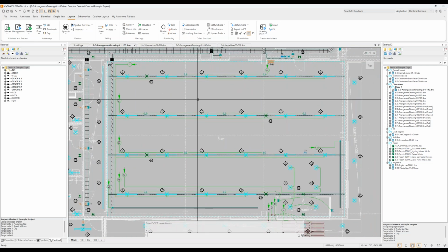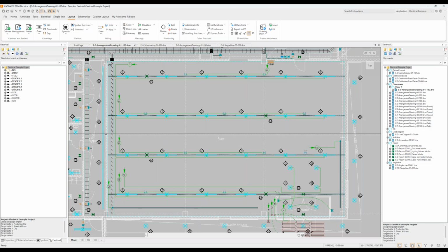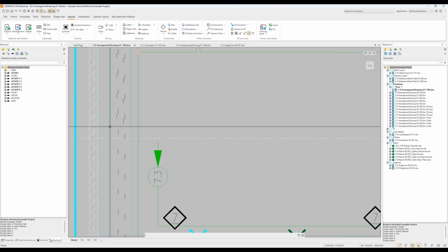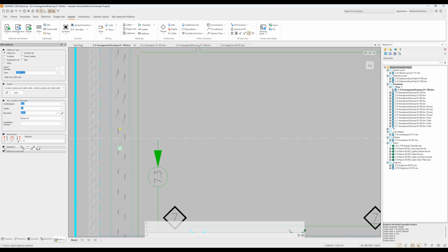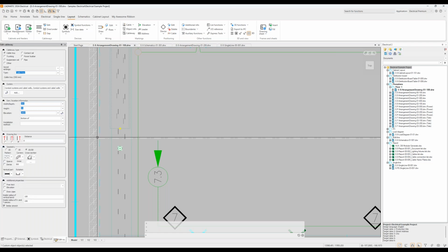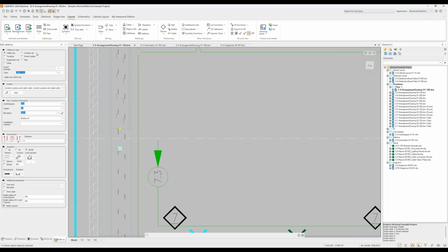Okay, that was just a quick example of how things are connected in electrical regarding cables, feeders, and distribution boards. Then let's move on to maybe doing more of the design of the drawing itself. We have the cable trays, cable ways, however you want to call them. We already have some existing things here that we can use as our base point. You can draw the cable ways, some trays, trunking, suspension relays. You can just read them here. You can define the types and save to be your default.